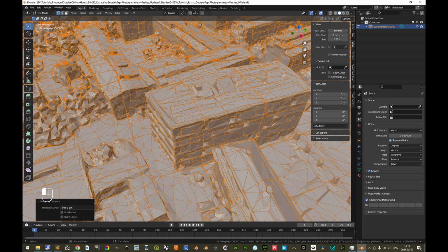Let's see if we can increase the merging distance to 10 micrometers and see if we get a discernible change or not. We dramatically reduced the amount of vertices. I still did not notice any discernible change. We will not be looking at this model this close, so if we do not see any change at this zoom in level, then we probably won't notice any change at a further more zoomed out level. We'll increase this to 25 micrometers then. And we are still hovering at slightly below 5 million vertices, so the merging distance might be adequately chosen.